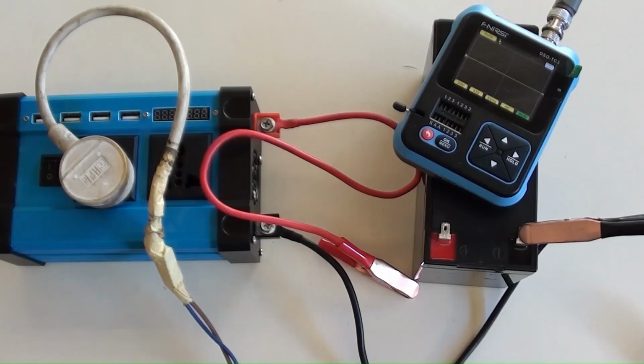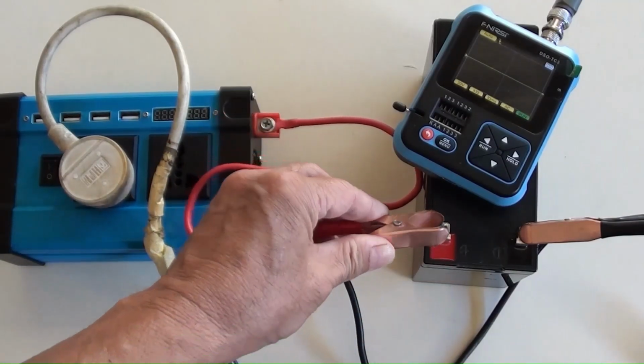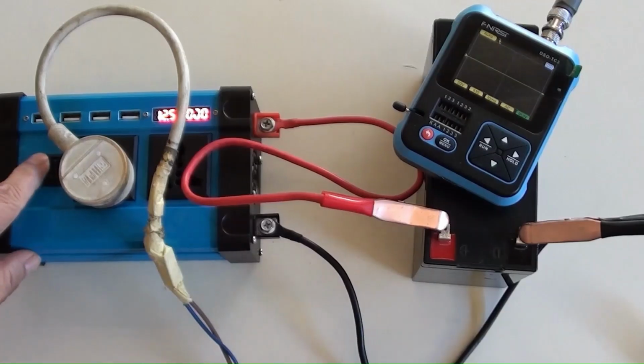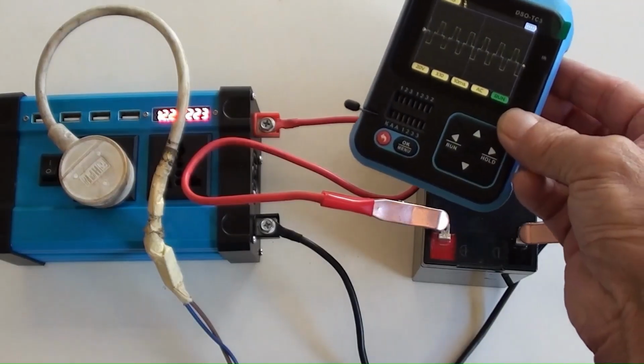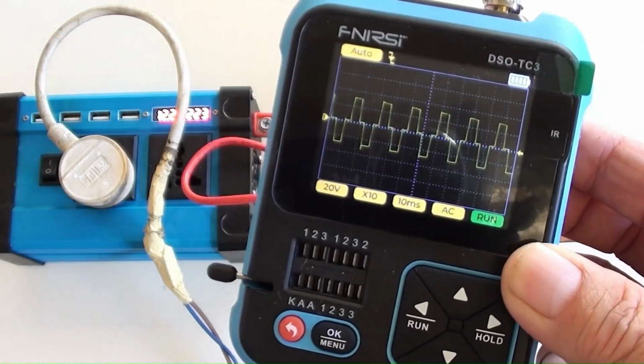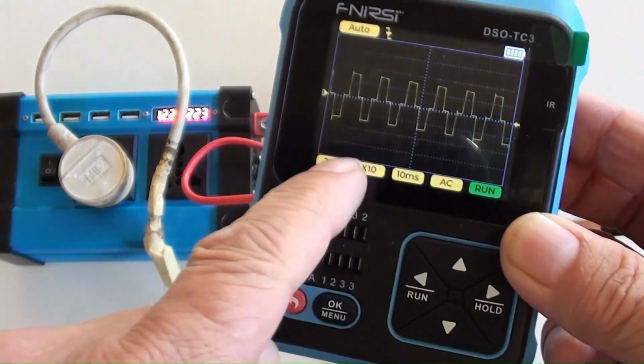This is a DC 12 volt to AC 220 volt inverter. It has been set up for showing its waveform of the output voltage with a mini oscilloscope. Switch the power on, we can see the output waveform is the modified sine wave. As long as the waveform looks like this, it can be converted to sine wave, with a couple of parts involved.